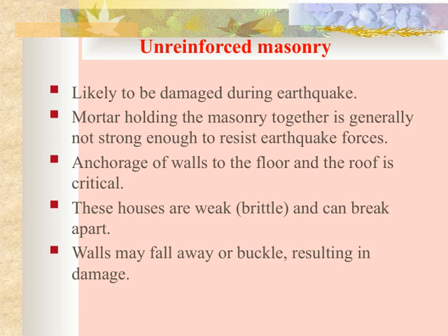Unreinforced masonry buildings are particularly vulnerable during earthquakes. The key issue is that they are likely to sustain damage when shaking occurs. This is mainly because the mortar holding the bricks or stones together isn't strong enough to resist the forces generated during an earthquake. Without proper reinforcement, these walls can easily crack or crumble.